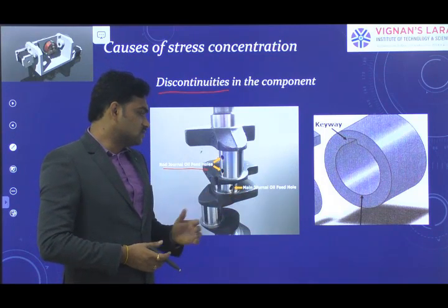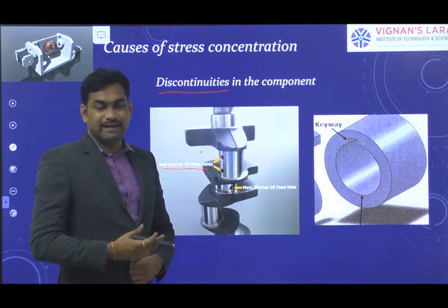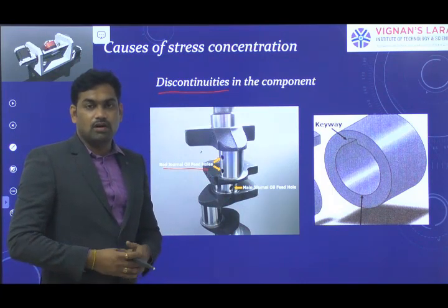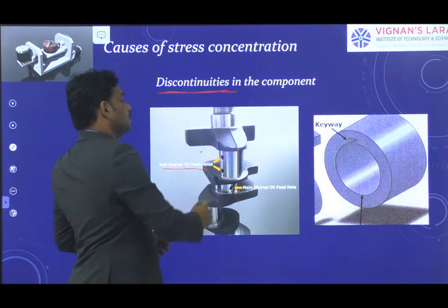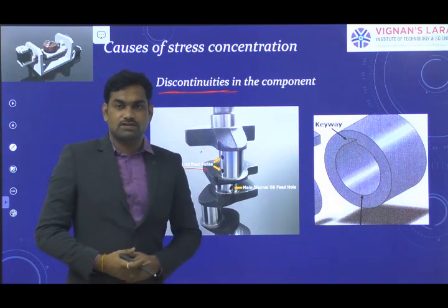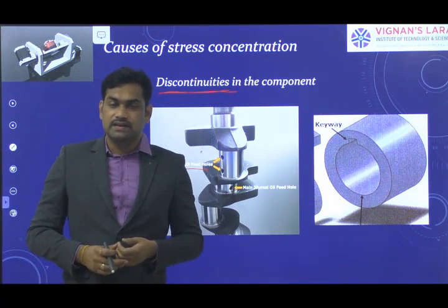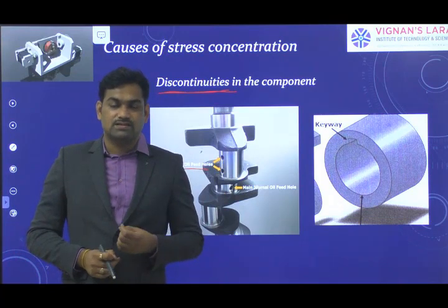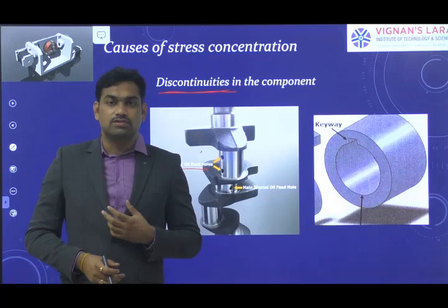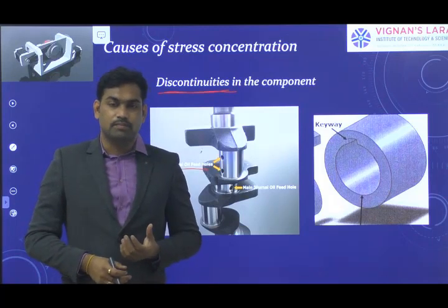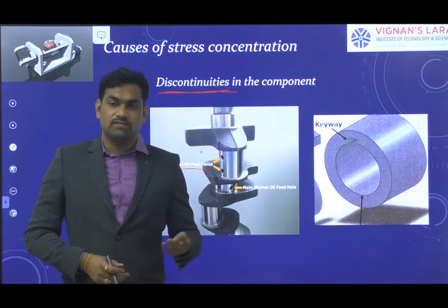So there is a chance of inducing a stress that is greater than the normal stress. Clear? So this is one more cause of stress concentration. Either variation in properties, in the sense of surface cracks or surface roughness, or foreign metal inclusion, or a weld bead, that is, a welding operation can take place. So that is one of the causes.